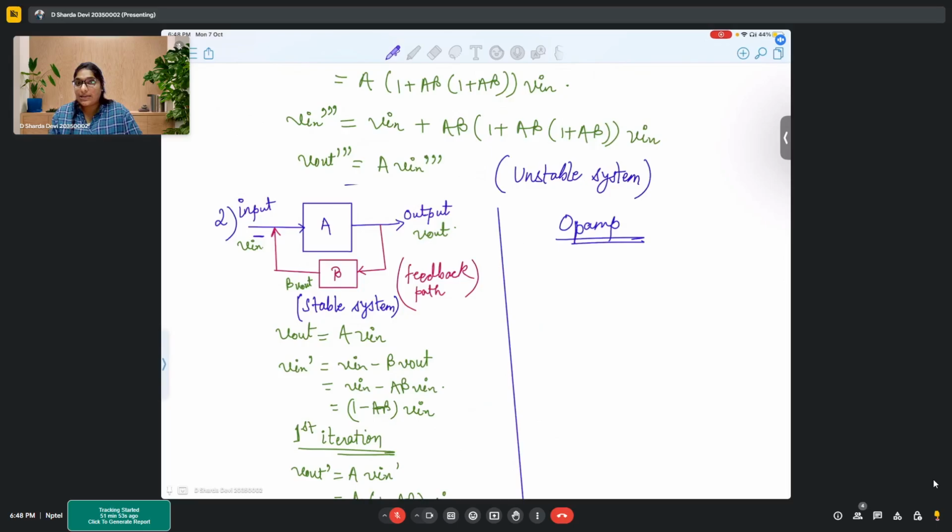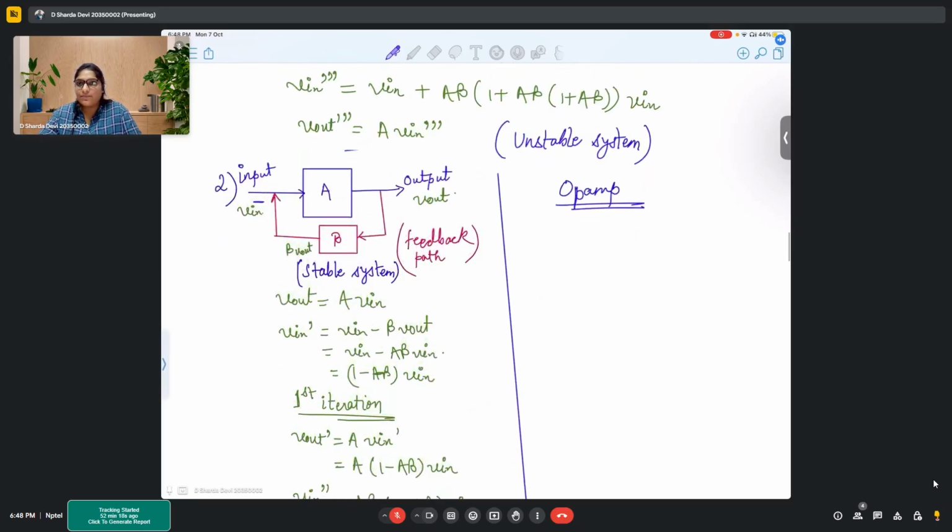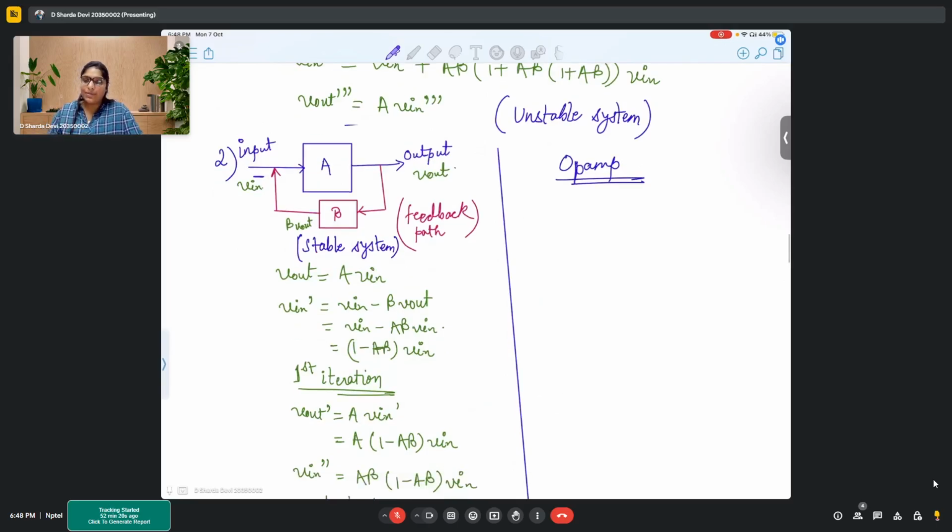When we talk about our circuits, particularly analog circuits that we have, most of the circuits we deal with are amplifiers or oscillators. So there, why do we need feedback? Especially, why do you want to reduce your output, right? If I have designed an amplifier, then why do I want to reduce its amplifying factor? Because at the end, if you observe a negative feedback, you get a reduced output, right? Your amplification basically reduces.